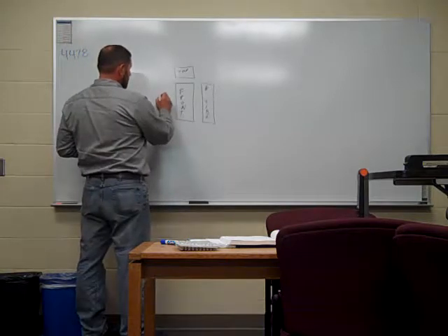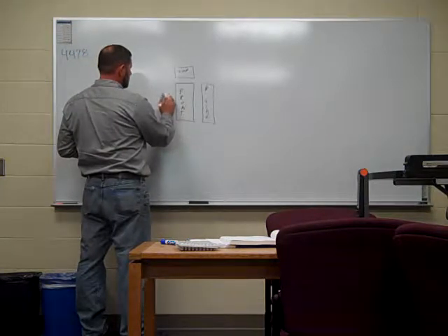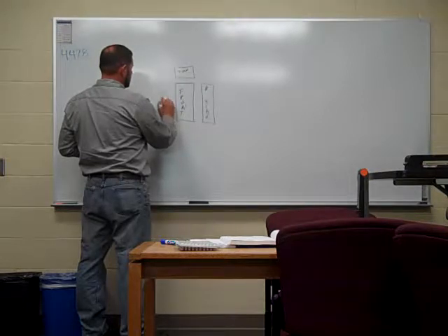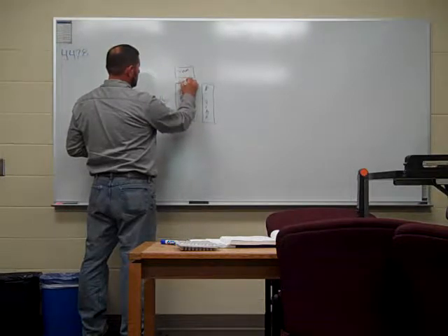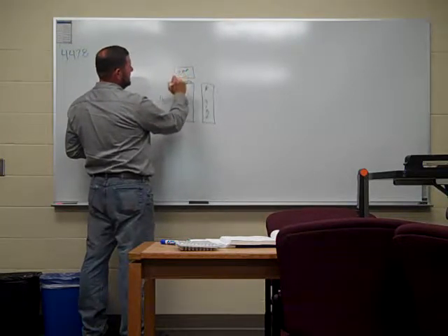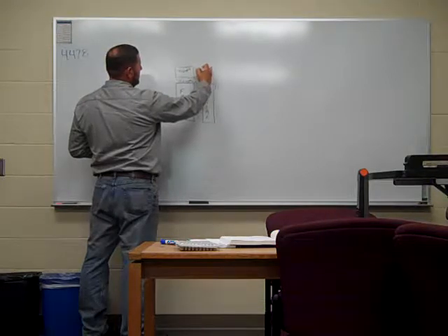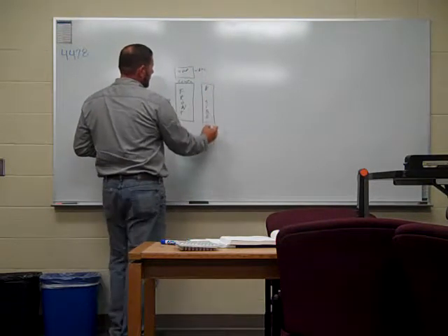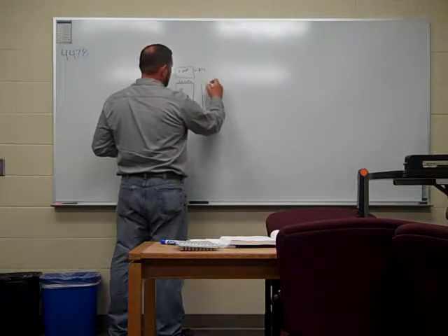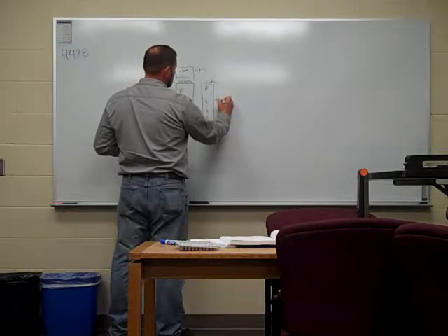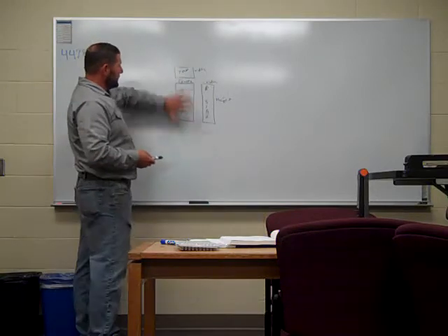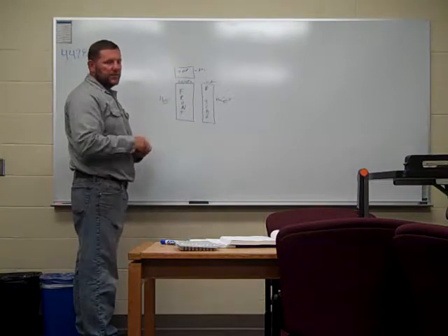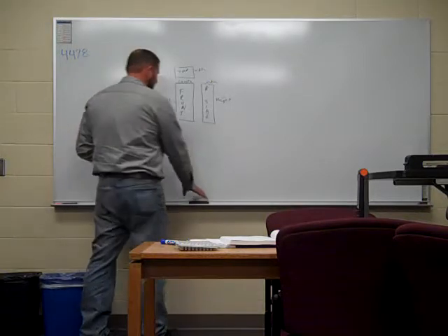Your front is always going to give you height and length. Top view is always going to give you the length and width. Same here, you're going to have height and width. So depending on what view you're looking at, that's the dimension that you're going to get. Each view, and it shows you right on page 120, follow that example, is going to give you certain dimensions.